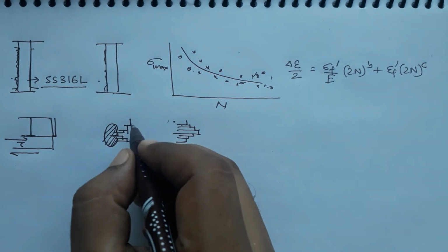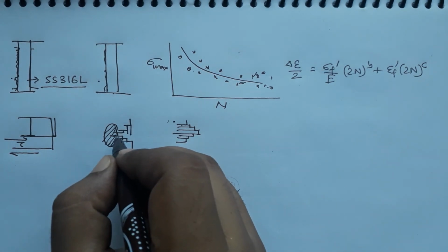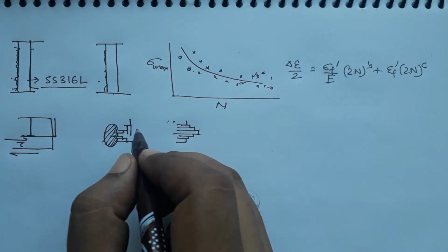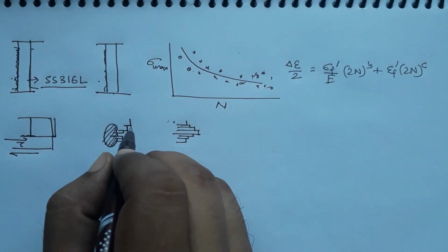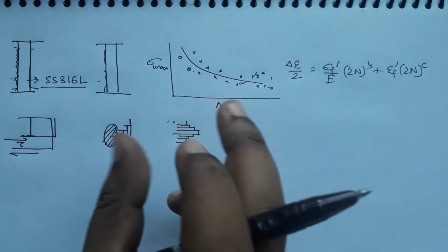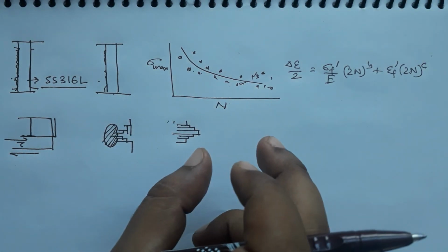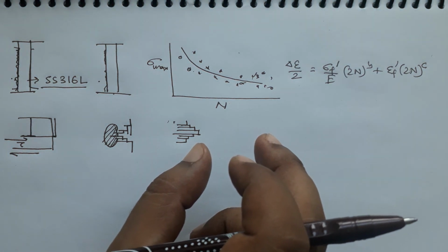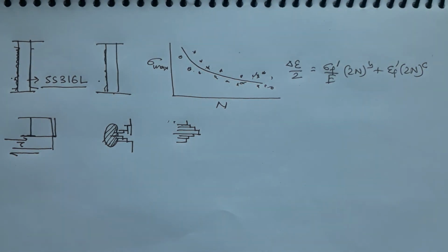This is not necessarily happening at the surface. It can happen at the grain boundary, and it can also happen inside the grain, where the dislocations are pushed so close to each other that they become a very, very small crack, a crack of an atomic scale.